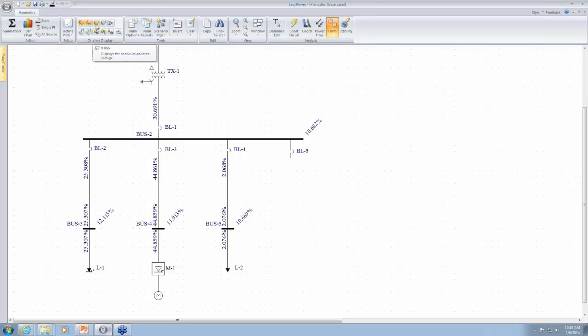There are other values like VRSS, that is root sum of squares, and the same principle for currents. We can also do VSUM. VSUM is a theoretical or hypothetical maximum possible voltage you might get if all the harmonic voltage magnitudes had the same phase angle. So what we're doing is just adding up the magnitudes. That's just a hypothetical value. It's rarely possible to get that exact same phase alignment for voltages.